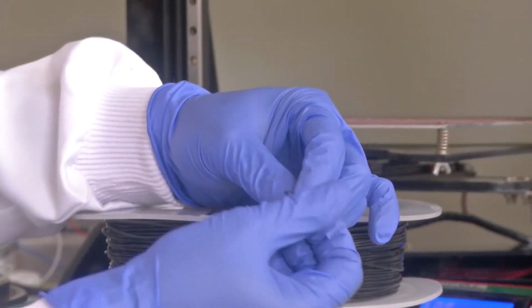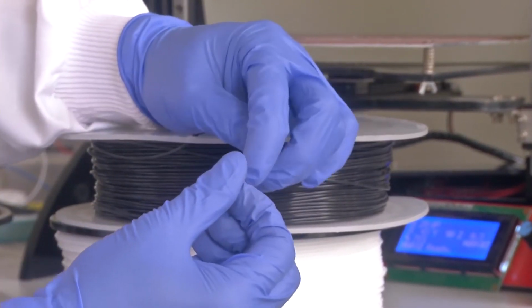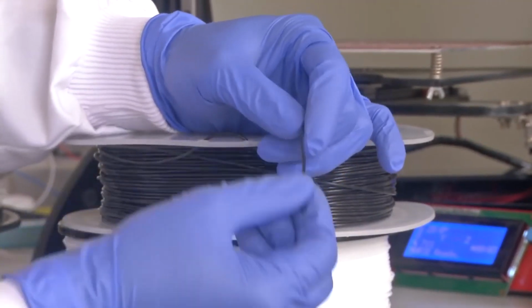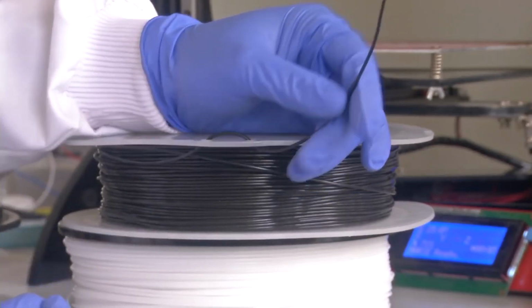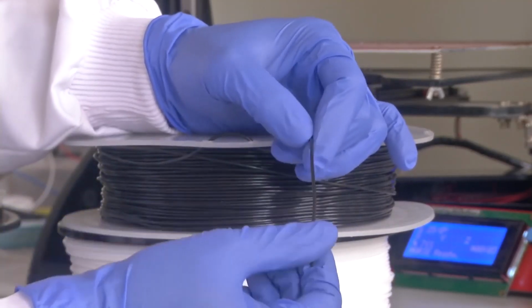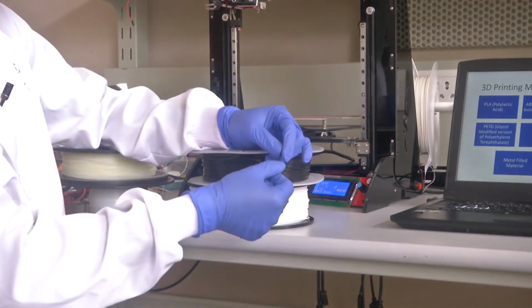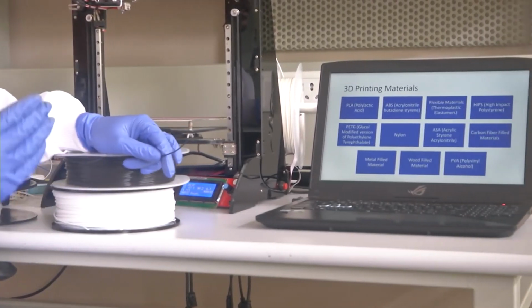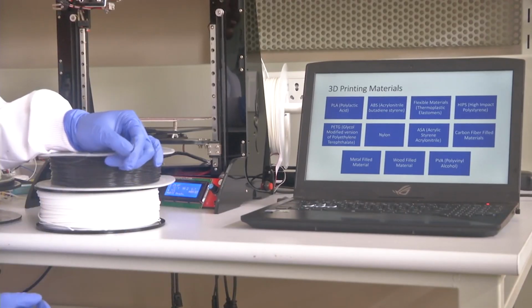Suppose this is a PLA material, and we need a material with more strength, but the properties like the melting point of PLA. The manufacturer will take fine powder of carbon fiber and mix it with PLA material to make this kind of filament, and the filament will have higher strength compared to PLA, but less than carbon fiber alone. So the material will be filled with carbon fiber fine particles.